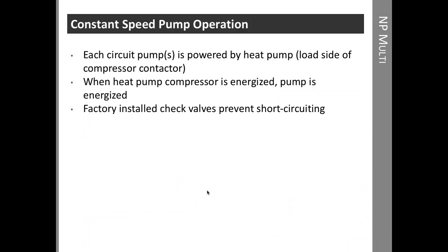As far as how this operates, each pump circuit, in other words, 1, 2, or 3 pumps, is powered by the heat pump, the load side of the compressor contactor. So when the compressor is energized, those pumps are also energized. And the factory installed check valves prevent short circuiting. So we're not going to have a situation where the water is flowing through the mechanical room rather than out to the ground loop.